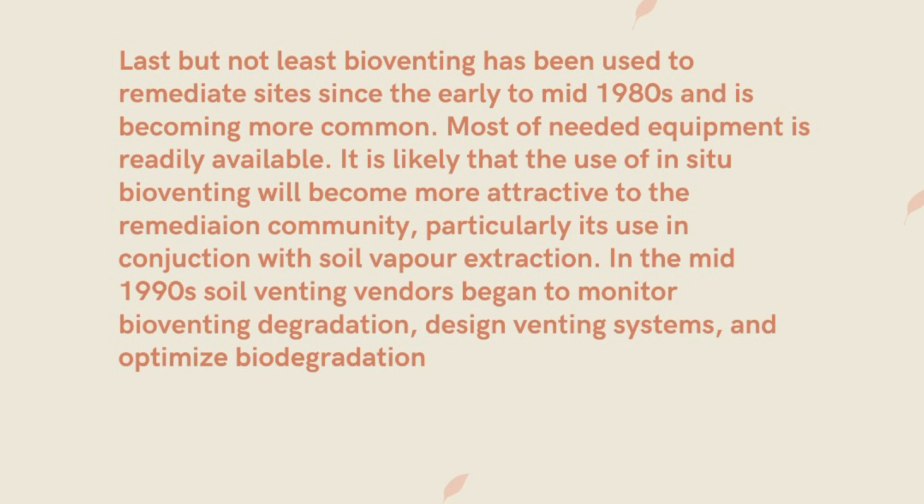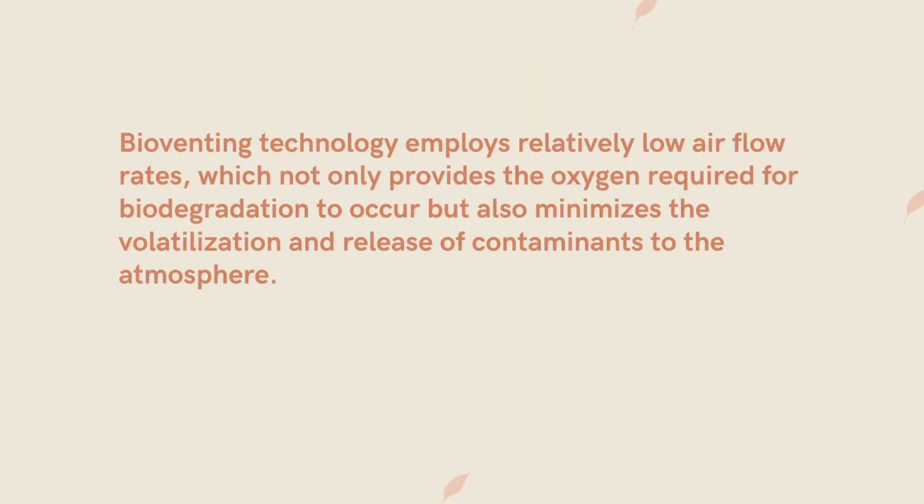In the mid-1990s, soil venting vendors began to monitor bioventing degradation, design venting systems, and optimize biodegradation. Bioventing technology employs relatively low airflow rates, which not only provides the oxygen required for biodegradation to occur, but also minimizes the volatilization and release of contaminants to the atmosphere.